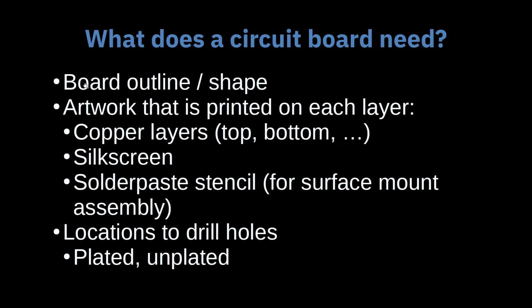And basically everyone's making circuit boards with a CAD program because that's what CAD programs are for. But practically, if you're making a circuit board, you really are just trying to make some artwork that's in a special fancy format. So you need a couple layers. You need an outline to show you what the outline of the board is. You need artwork on each layer. So you need 2 copper layers at least, a top and a bottom. And you need a silk screen, solder paste.